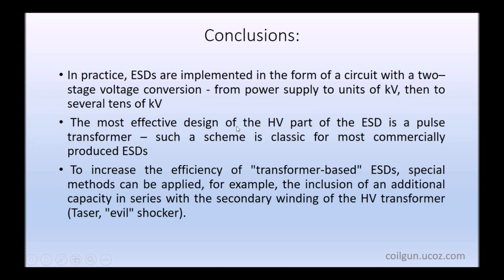The most effective design of the high voltage part of the ESD is a pulse transformer. And to increase its efficiency, we can add some measures, for example, an additional capacity in series with the secondary winding. On this principle are based Taser and the so-called Electroshok in the Russian language.